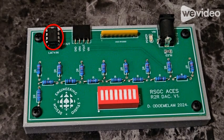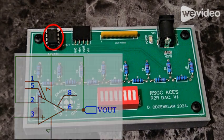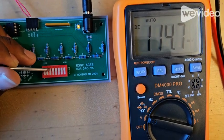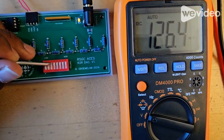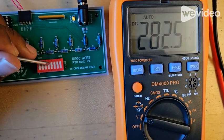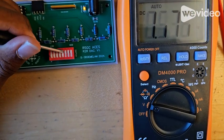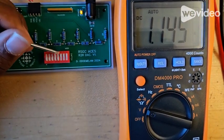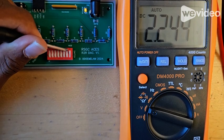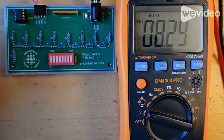The way it's wired, the op-amp has unity gain, which means the output voltage is the exact same as the input voltage. What makes it useful is its ability to buffer the circuit. Without a voltage follower, the output of the R2R ladder might be affected by the load that it is connected to, and any device that draws current from the DAC could cause voltage drop, making Vout unstable. The voltage follower prevents this by providing a very low output impedance, meaning it can supply enough current to drive a load without causing the voltage to drop. It effectively isolates the R2R ladder from the load, ensuring that the calculated analog voltage remains accurate and stable no matter the load that is connected.